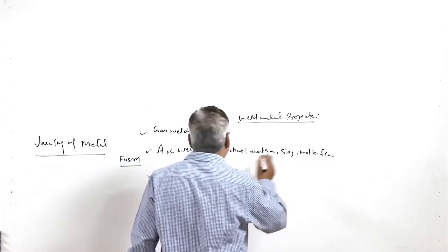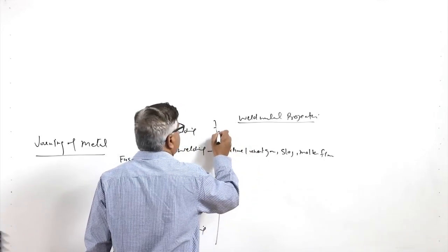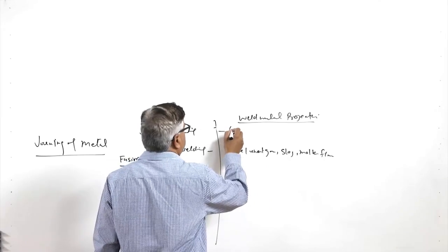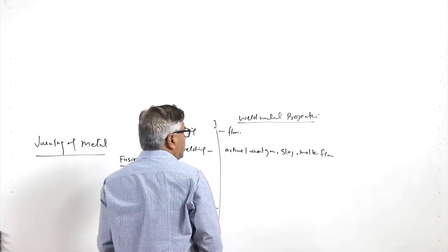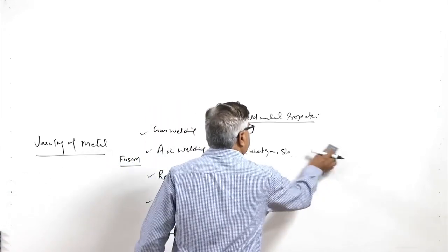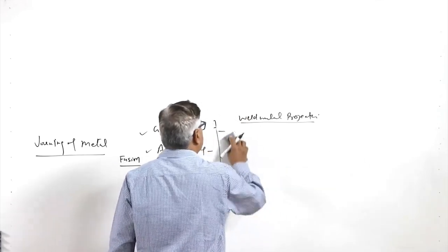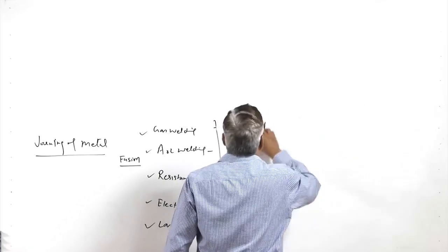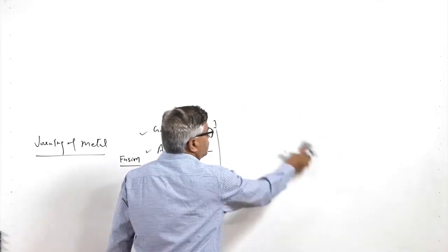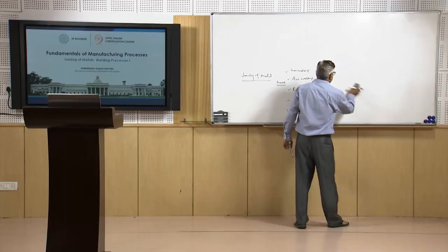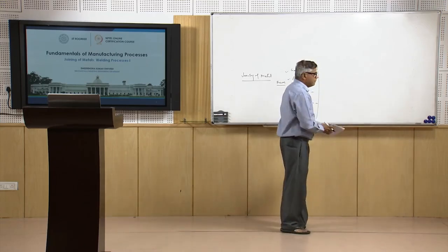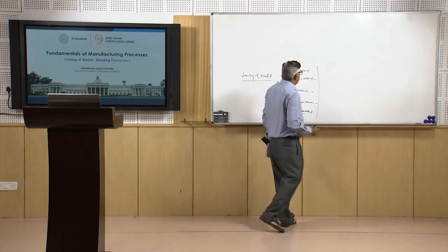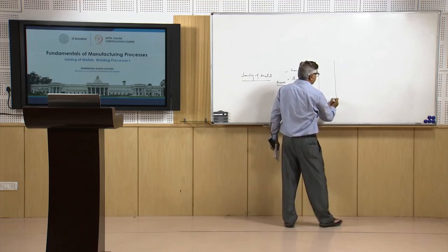In gas welding, normally no protection approach is used, except in some cases flux may be used in order to deal with the problems of oxidation. So, since the different processes offer different kinds of protection or use different approaches, that is why the cleanliness of the weld with regard to the presence of oxygen and nitrogen in the weld is different in the welds produced by the different welding processes.